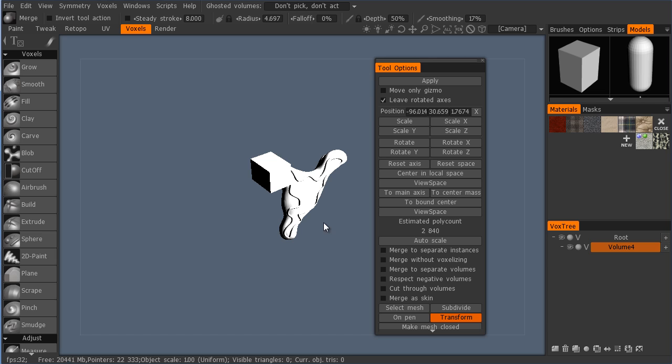So what you need to do is, if you have a look in this area that is estimated poly count, try and make your piece bigger until that's at about 3, 4, 5 million polys. All that's going to depend on your RAM. There are not actual polys, it's estimated what they're going to be if it had to draw a mesh around that. So you need to scale that up. I don't know, let's try, I find for jewelry about 3000 gives you a good size.